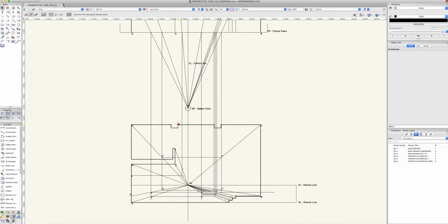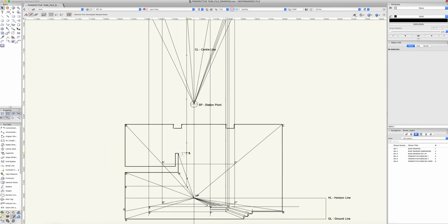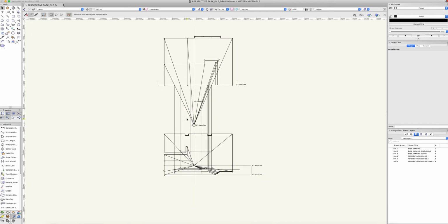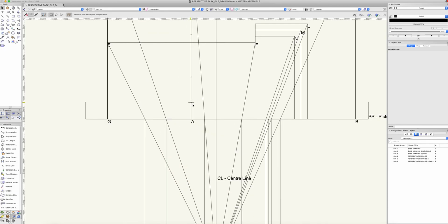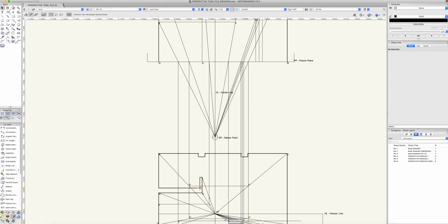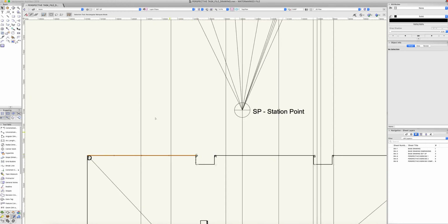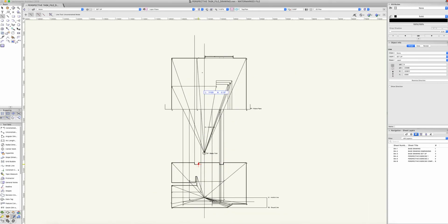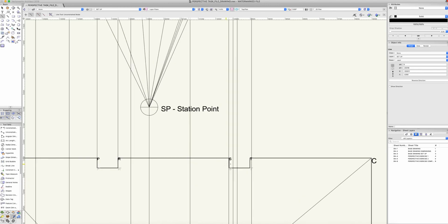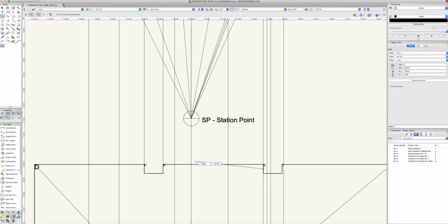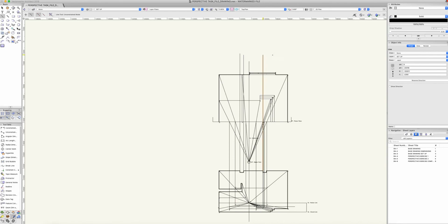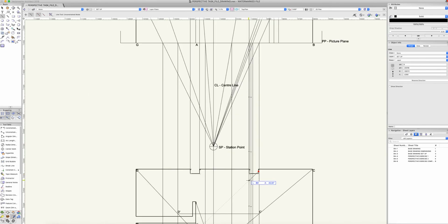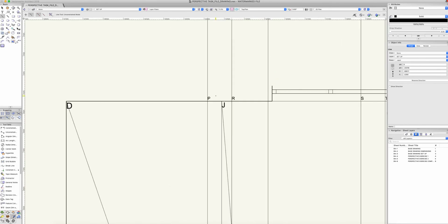We need to understand where this is located on plan in order to find out where it intersects the rear wall. So unlike the mezzanine, where we had this line drawn already, which showed the front end of the mezzanine, we just need to draw a couple of guidelines from the beam and take these back up through the plan. We do this for both. So we've got a point from P and R, and we're going to do the same from S and T. So we can locate these on plans.